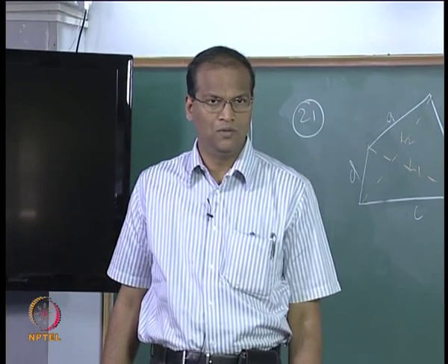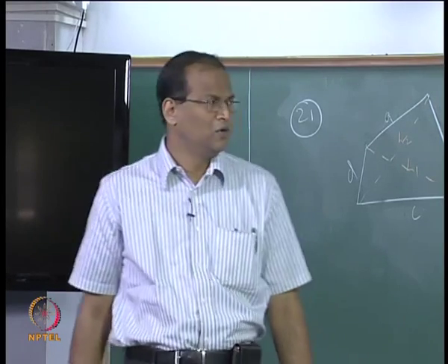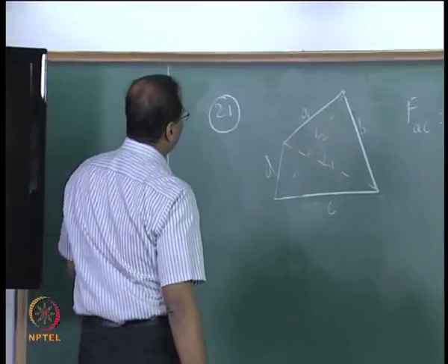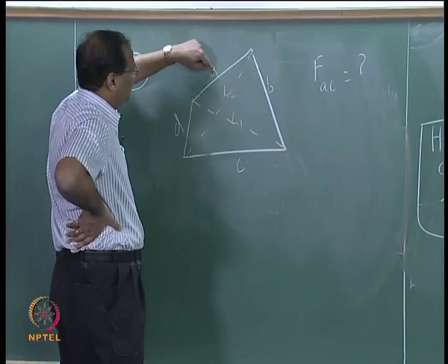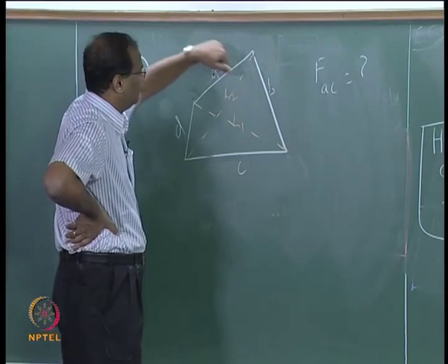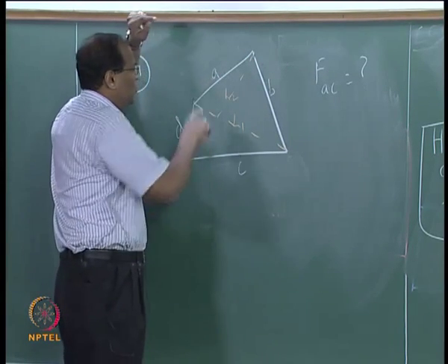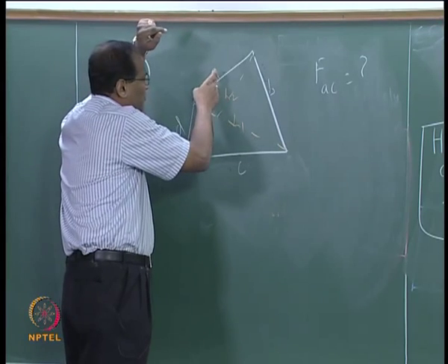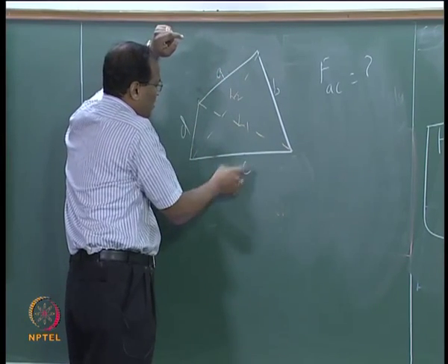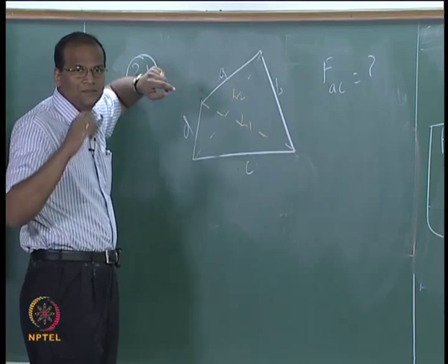Changing the physical situation, because you are changing the enclosure itself. No, but if you look at the energy balance, the sum of FAA plus FAB plus FA to this must be 1. So whatever is going to C and D must come through this imaginary L1, there is nothing wrong in that, that is the energy balance.